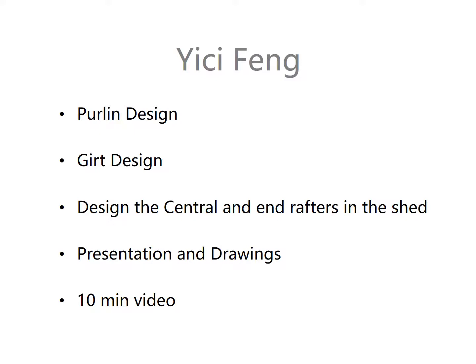At the beginning of the purlin and girt design, we can find the wind load is a very important part for them, because a different region, different terrain category, or topography can lead to a different wind class. And the wind class is the most important factor to determine the wind load. From the wind load, we can calculate the combinations of dead load or live load.